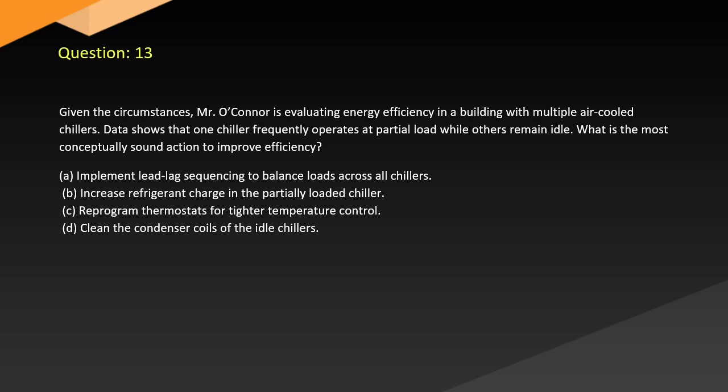Question 13. Given the circumstances, Mr. O'Connor is evaluating energy efficiency in a building with multiple air-cooled chillers. Data shows that one chiller frequently operates at partial load while others remain idle. What is the most conceptually sound action to improve efficiency? A. Implement lead-lag sequencing to balance loads across all chillers. B. Increase refrigerant charge in the partially loaded chiller. C. Reprogram thermostats for tighter temperature control. D. Clean the condenser coils of the idle chillers.